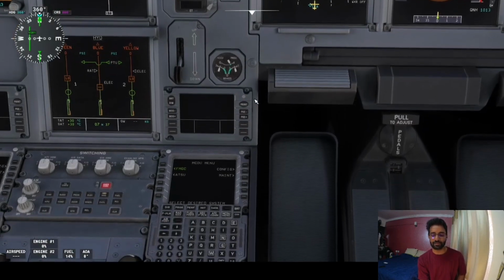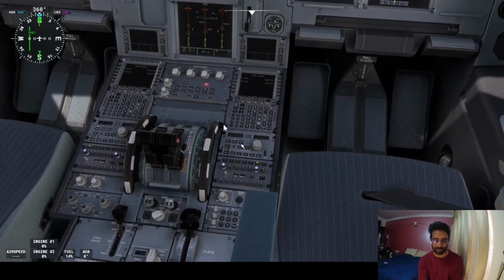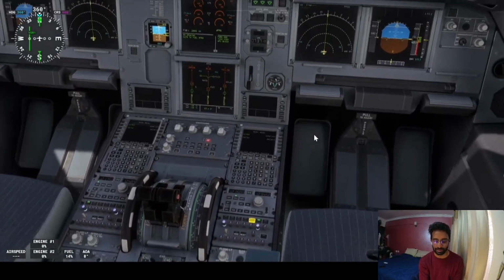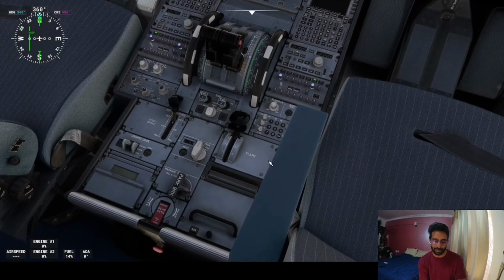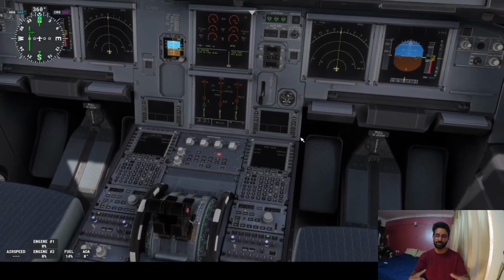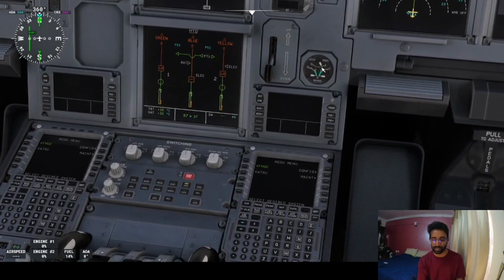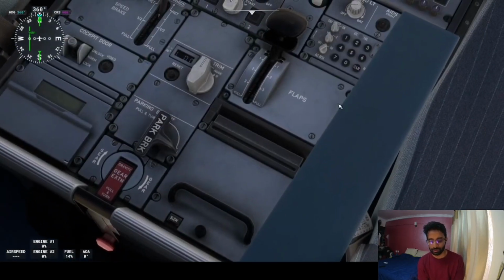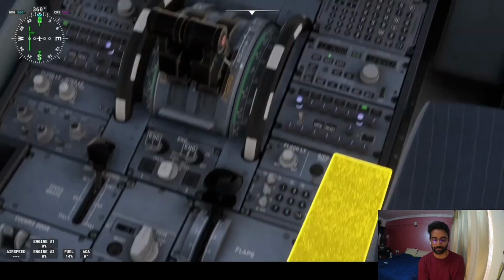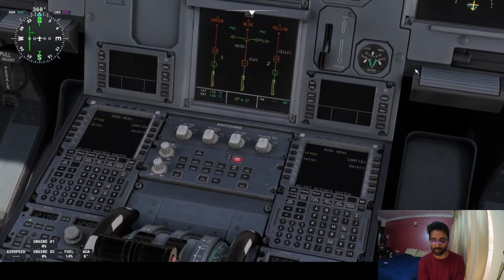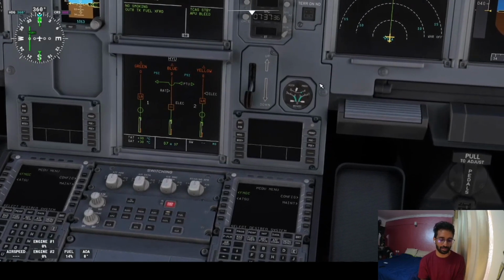So let's see what happens if accumulator loses its pressure. Again, ignore that this button is in. Now I fixed it. Let's see. If I keep operating the brakes multiple times, the accumulator will use this action a lot of times to pressurize the brake. See, I turned off the parking brakes. What do you see? Accumulator still has some pressure in it, but you can see the parking brake pressure has gone down to 0. There is no wheel pressure anymore. So keep doing this. Every time I do it, notice that the accumulator is losing a little bit of pressure. If I keep doing this, it's not correct to do it all the time like this multiple times, but let's see what happens.